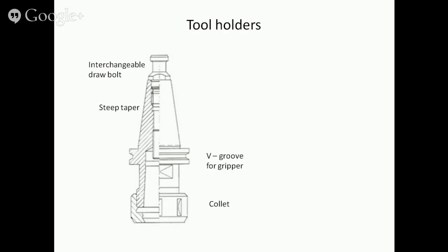There are several standards, among them SK, DIN, German standard. Its taper is 8 degrees and 45 minutes. BT, which is a Japanese standard, and CAT, which is a US standard.